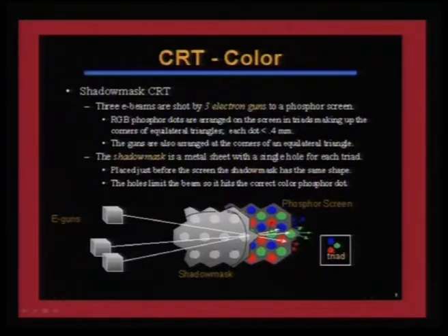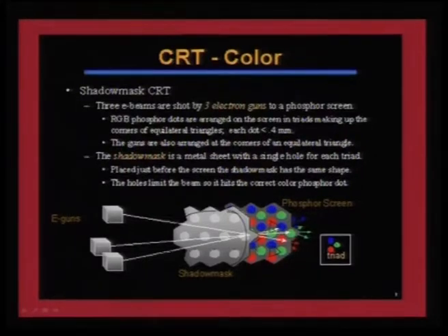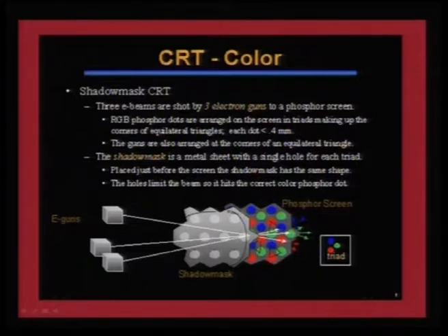If you can follow here, I can draw a triad like this at any given place. So, each triad forms a pair, and each of this triad can actually be injected with an appropriate cathode ray which has a different energy, and depending on that the mixing of these colors occurs.